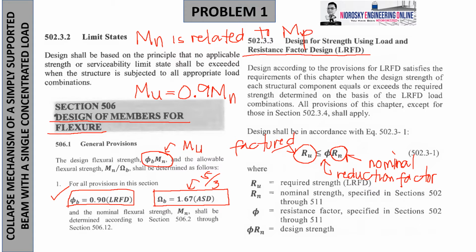So somewhere in the middle, we can safely say that M sub n should be less than or equal to the plastic moment, since the plastic moment, as discussed already in one of the theorems, sa tatlo yan, and we need to understand the second theorem, that no value more than the plastic moment, pagka tiningnan natin yung pinaka generalization niya. So this will be also the same concept that we are going to use every time that we discuss flexural analysis, that the nominal moment should not be more than the plastic moment. So therefore, there is a correlation between the two.